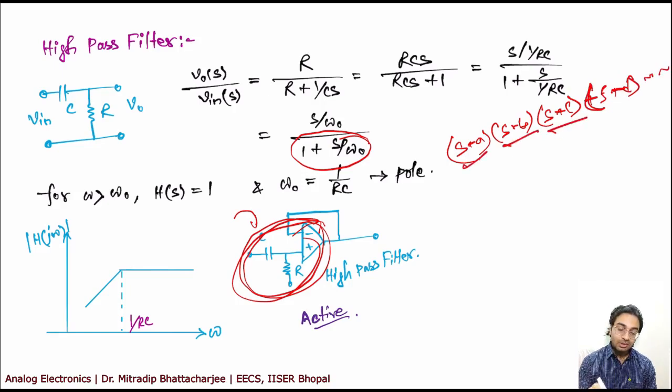So for each section you need one such thing. So what does that mean? You are improving your characteristics. Definitely you are probably imposing 5 poles into a single point, and this will give you 100 dB per decade decrease. But as you increase the sections, cost associated with the filter will also increase. Now there the problem lies. If you have money, I can make this kind of filters.